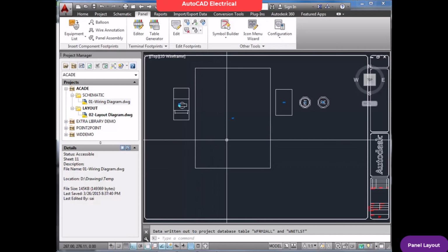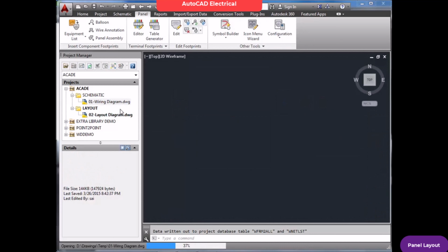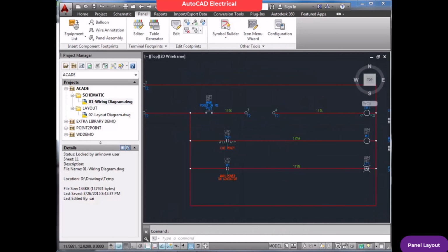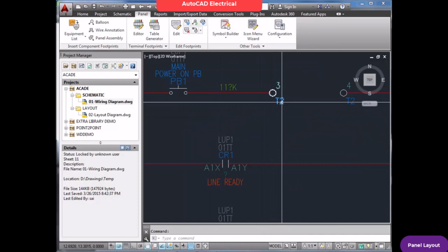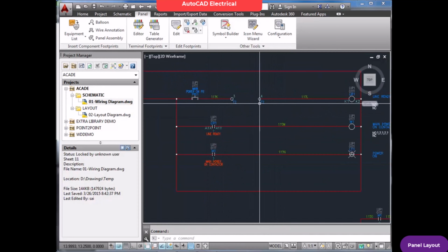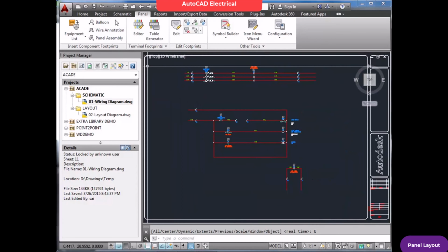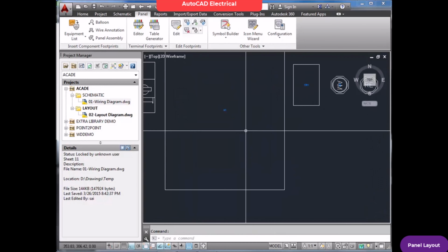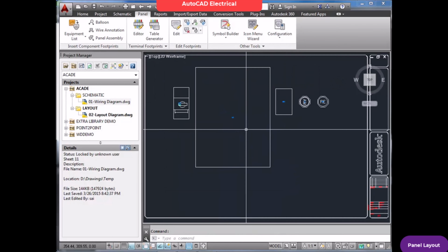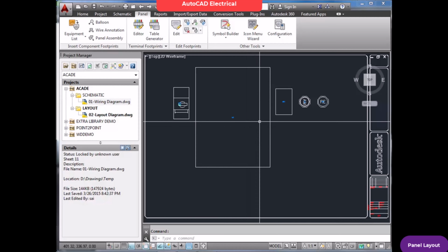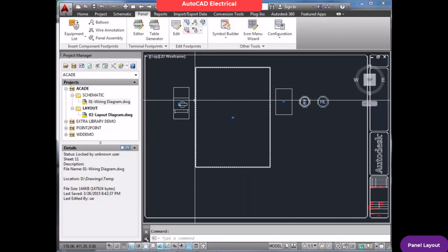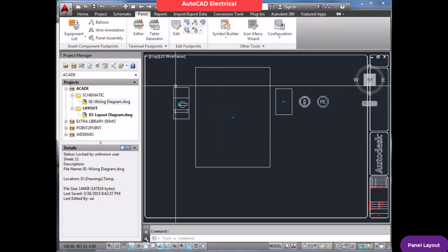Now if you want to insert the terminal details, the termination, I mean this particular TB is connected to which element and all those things, how can we do that? Mainly when you submit this drawing for manufacturing purpose, the wireman may require that termination details so that it will be easy for them to trace the wires. So this is one of the best features.